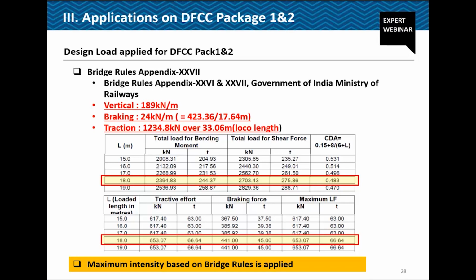So this is a very useful table when you design the bridge rather than RSI. However, because this 5 load combination is quite complicated, and as I explained, the UIC code specifies 2 loadings, and in terms of braking and traction, they specify just a certain equivalent uniform loading.